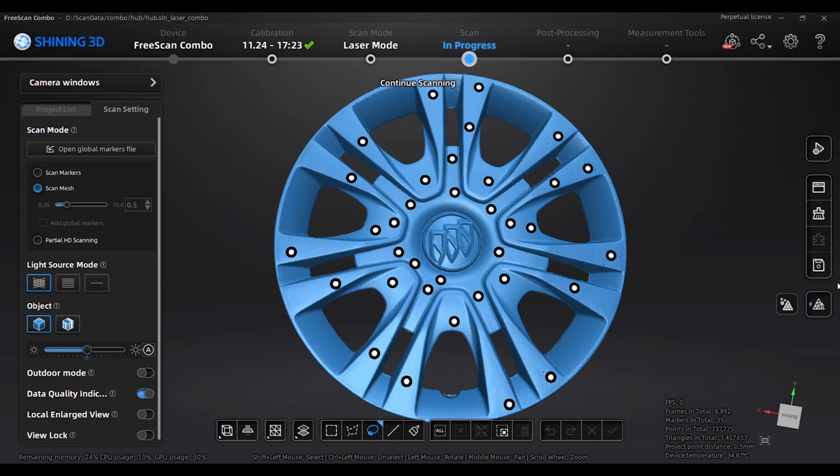We provide two mesh options, mesh processing and mesh optimization. You can use the mesh optimization if you find a slight misalignment on the data. It will optimize the data first, using the global markers, and then do the mesh. Else, we suggest mesh processing directly.